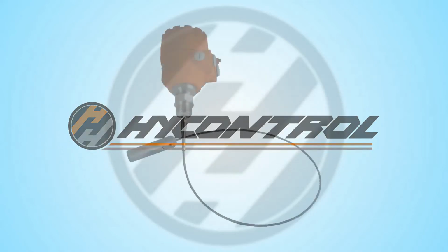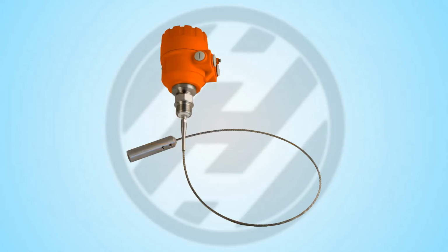We're going to look at installing and programming a Hycontrol VF04 TDR level measurement transmitter on a standard silo. TDR can measure liquids or solids. In this instance we'll be programming for a solid product. VF04 TDR can be supplied with probe lengths of up to 24 meters, which can be cut shorter to adjust the measurement range. This will then need to be entered during the programming stage.